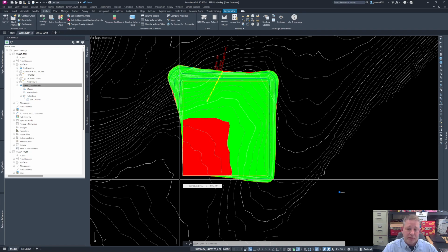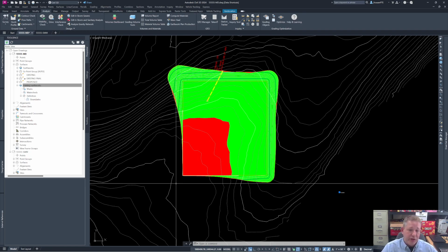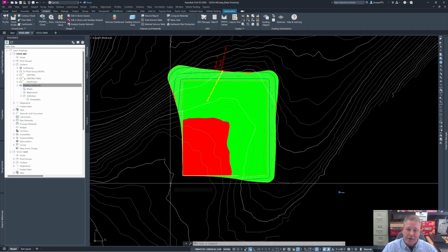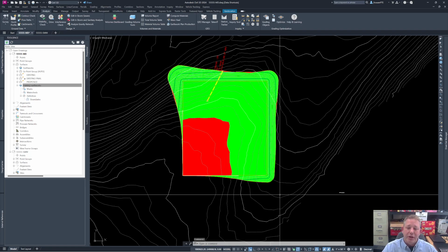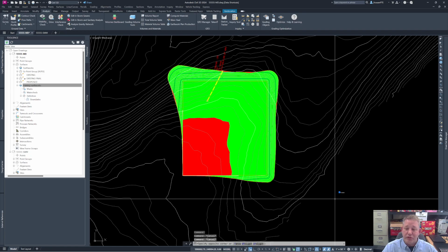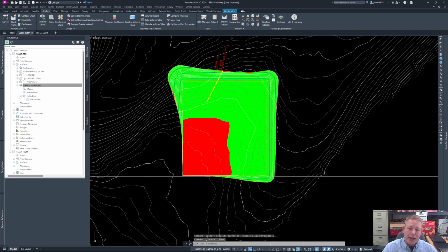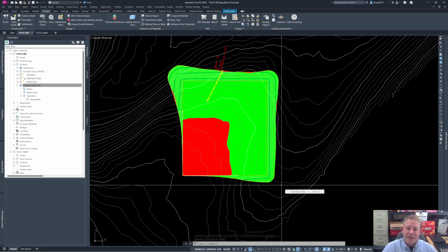We have forms, we have Excel sheets that help us calculate the thickness of subbase, pavement, those kinds of items, and trenching, to give us a little bit more accuracy. But if you're looking for a quick earthworks, this is surface to surface. It will give you a really fast answer, to give you an idea if you're in the ballpark as far as balancing the site.